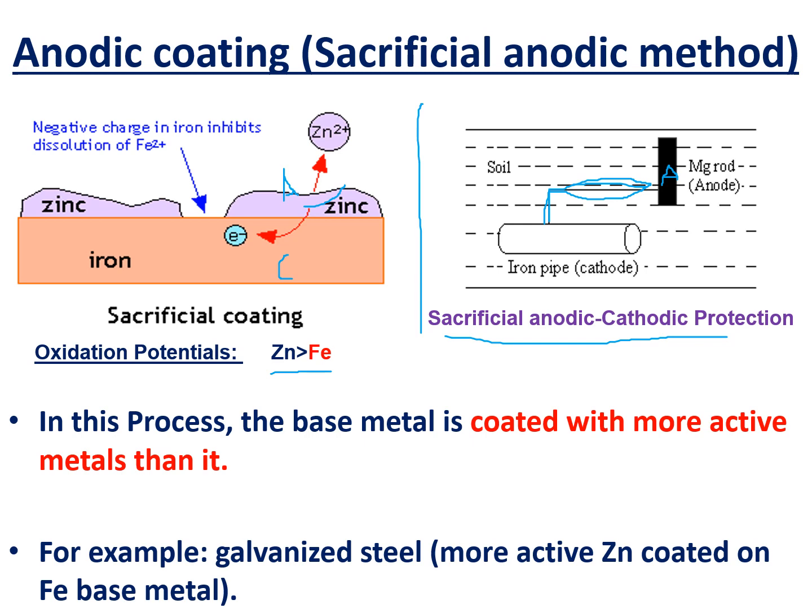Okay, so when you make a zinc coating on iron metal, and you use that object, some damage will happen on the surface of the iron. So now iron is exposed to the air. Who is involved in corrosion, iron or zinc? Because here iron always acts as a cathode with respect to zinc, and zinc acts as an anode.